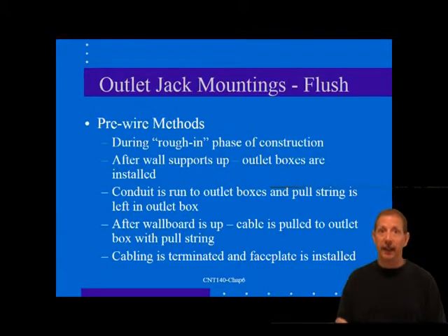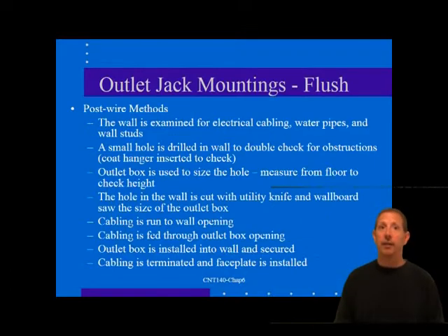After the wall sheathing is in place, and usually after the wall has been finished or prepared, each cable is then trimmed to working length and terminated in the jack. The assembled outlet is then mounted in the box or ring. Using the actual cable in the rough-in stage can present some problems if you're planning a full Cat 5e or 6+ installation. The cable is left exposed and subject to damage by others during the construction. In addition, you must coil up the wire very carefully to avoid the sharp bends and kinks that can disturb cable performance at the category of operation.